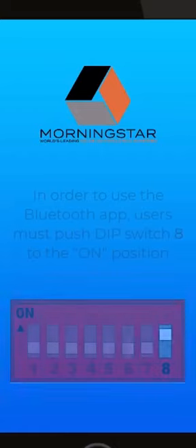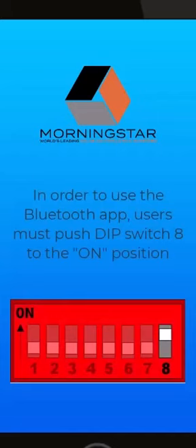In order to use the SureSine utility app, the user must enable Bluetooth communications with dip switch 8 up before connecting DC power to the inverter.